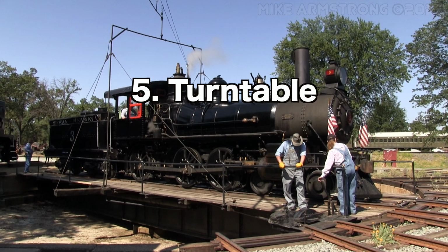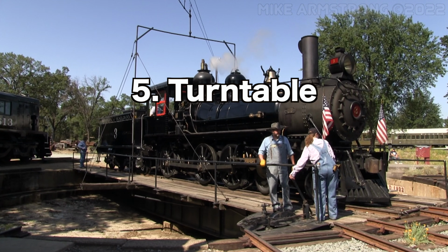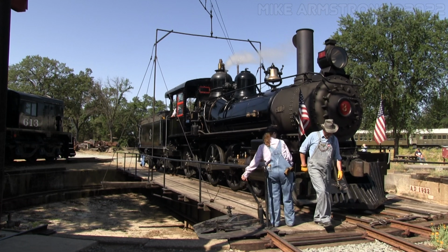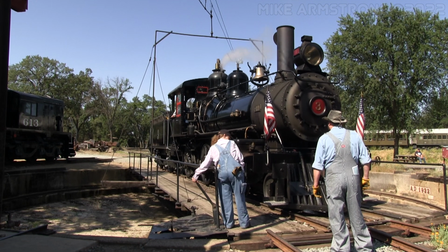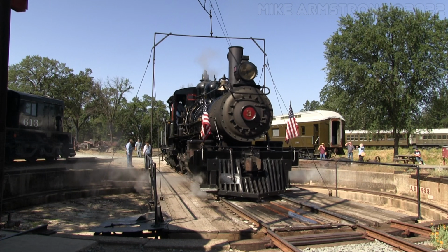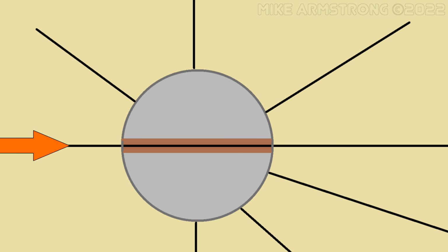Finally, we come to the fifth option for turning trains on our list, the turntable. A turntable is a section of track that is built onto a rotating deck and placed within a circular pit. The deck pivots from its central point, allowing it to travel in a full 360-degree circle within the confines of the pit. They can turn one or two pieces of equipment at a time in any desired direction and are either powered manually, often referred to as Armstrong-style turntables, or with a motor drive.